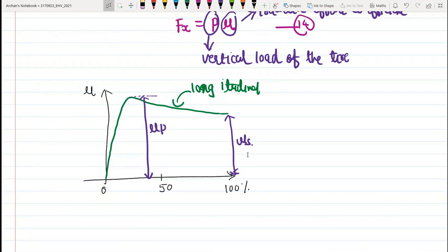And whenever we have the lateral slip of tires, at that time the curve will be like this. It will be maximum, then it will increase, and when slip becomes 100%, the tractive effort, or sorry, not tractive effort but tractive effort coefficient, will become 0. This is our lateral case, right? So this is what we have seen, the relationship between the tractive effort coefficient and tire slip.